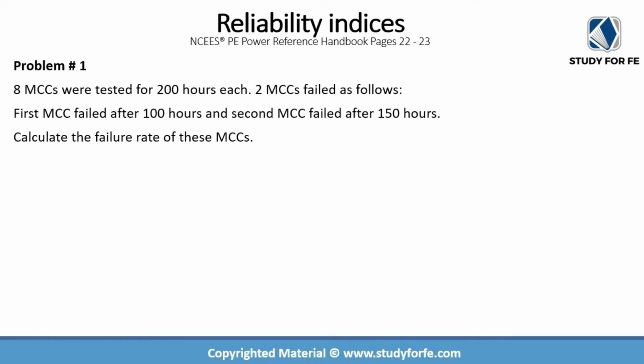Let us now take a look at a practice problem involving failure rates. So we have 8 MCCs that were tested for 200 hours each. 2 MCCs failed. The first MCC failed after 100 hours of service, and the second MCC failed after 150 hours of service. So we are being asked to calculate the failure rate of these MCCs.